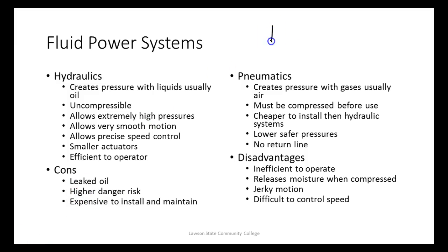anybody know the basic formula? Pressure times area. So how much force we generate is how much pressure we have and how much area we push it against, right? So if I have 1 pound of pressure and I push it against 1 square inch of area, then I would create 1 pound of force.